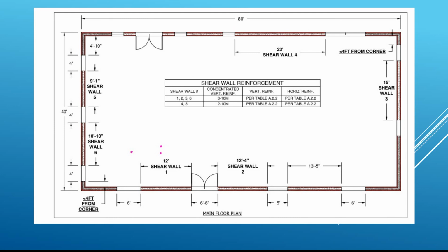I'm not sure, when it comes to a walkout, how you're going to deal with it. The walkout may not be the full width of this whole end wall. It may end up being two 4-foot pieces here, right? Or you might have a 12-foot here and there. So again, these shear walls really throw a little bit of a wrench into things.